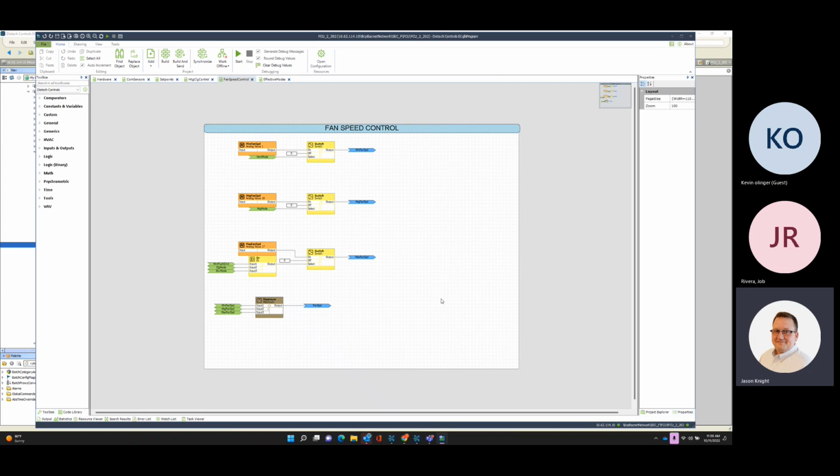So all these jobs we've been doing for the last 5 years, on paper it says we can run this down to 1%, 3%. Well, we do that and the motor doesn't actually turn. We do that, the CT won't even read that low. There aren't any manufacturers out there that make a current transducer or current switch that reads below 0.25 amps.